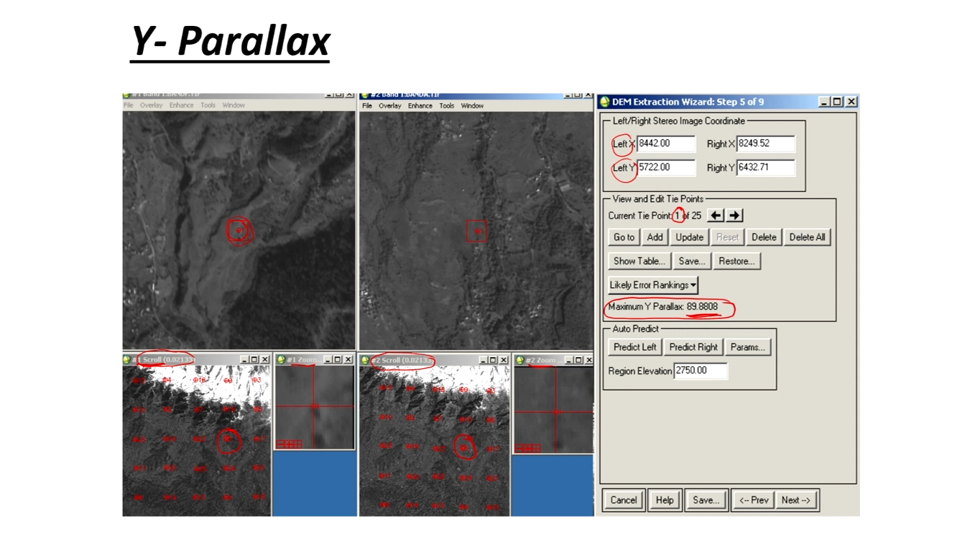For example, I want to correct the location of my tie point. First you have to delete this point and you have to choose a common location. For example, in this image you first have to see which two areas or which object you can clearly identify in both images, in band F and band A, and you select one similar object.